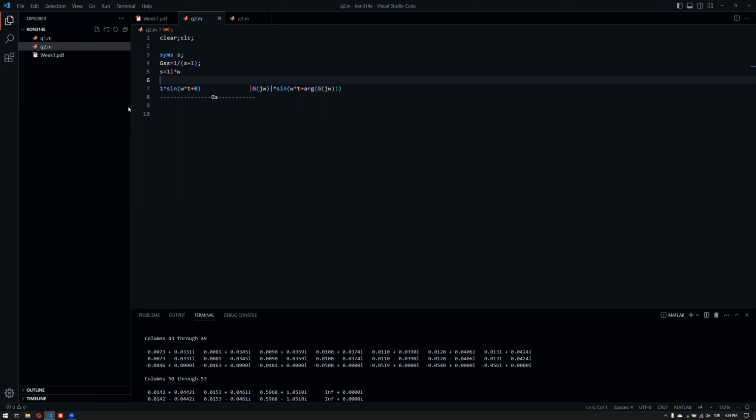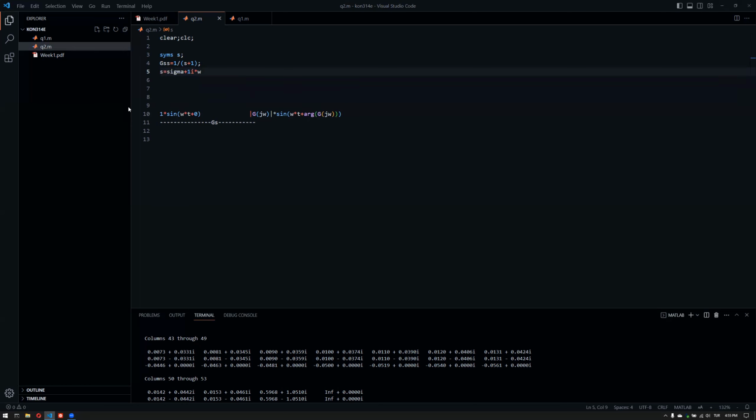Now, you can check the Laplace transform integral and the Fourier transform integral, and you will see that the only difference is that if you plug in s equals j omega, it's basically going to be the same integral and same transform. But keep in mind that s is a 2D domain where we have sigma plus j omega. So it's a 2D domain that we're talking about when we're talking about the s domain, whereas the Fourier domain is only on the j omega axis on its own, because sigma is by nature equal to 0. So we don't really consider something that has sigma in it. We're just directly on the j omega axis, which is quite important for us if you think about stability.